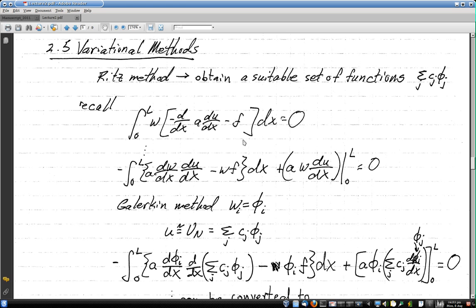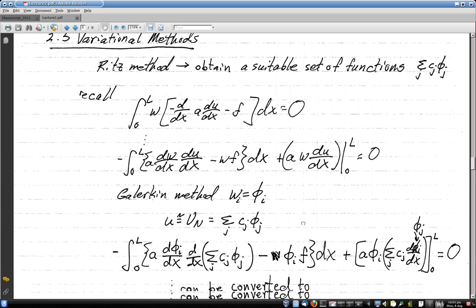So you have these weight functions, phi sub j. Here are the unknown constants at the nodes, and we substitute that into some strong form, or actually here's my strong form, the integrand times the weight functions. Through integration by parts or the product rule, you manipulate the derivatives. This changes from solely an integral equation to having points on the boundary that you have to evaluate.